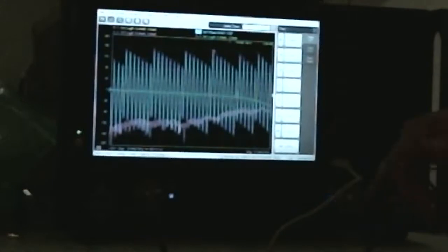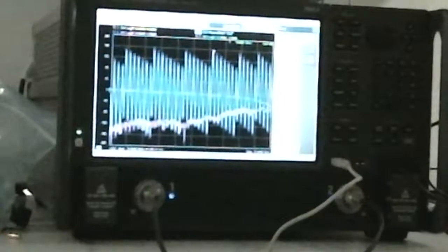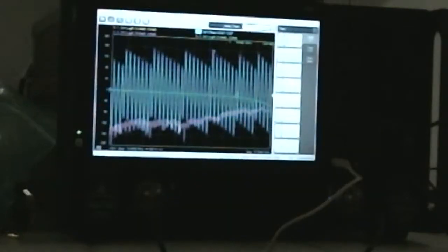And again, you have to think about what the scale is. This is 180 degrees, or 45 degrees per division. So this is changing 30 degrees based on me flexing the cable like this. 30 degrees on the Smith chart, no way you're going to match. So again, it may work for a few hundred megahertz, definitely not going to work for 3 gigahertz. So it depends on where you are going to do your measurements.